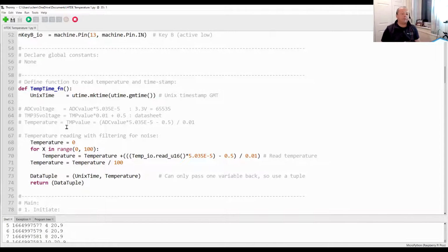Now, here is the first real gotcha I have discovered with the RP2040. The RP2040 cannot handle very large numbers, and it cannot handle very small numbers with many decimal points. It will start to approximate everything at those extremes, and start giving you really screwy results.